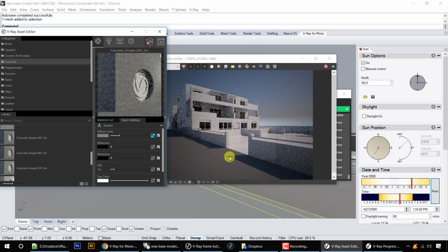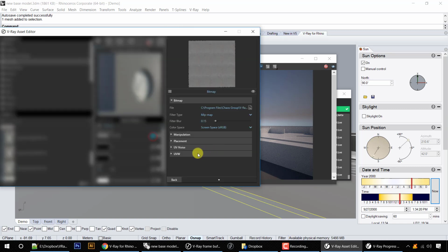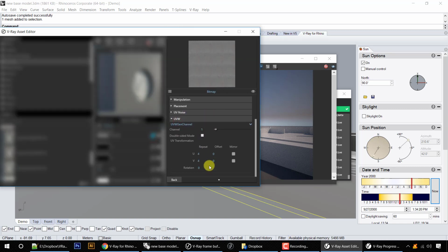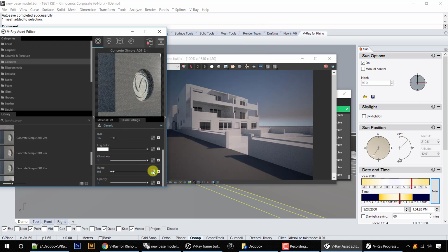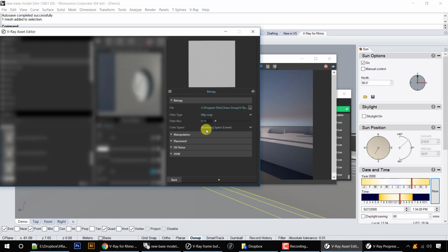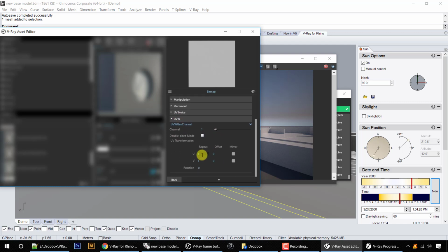You kind of have to get the feel for it, but you can see the difference. If it looks like you took one picture and stretched it out over an area that's too large, you'll be able to tell in your rendering that you need to adjust the tiling. We'll talk more about this in the other video, but I just want to mention it. The other thing you do is go to the bump map. The bump map is a black and white map that makes kind of 3-dimensional indentations, and you have to make sure that tiling matches the other map, otherwise it's going to look funky.